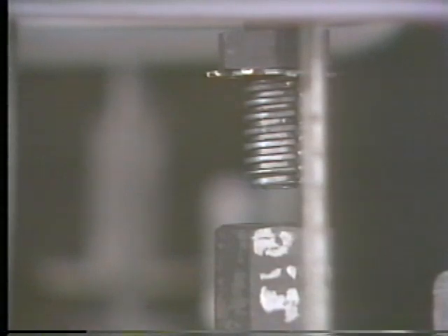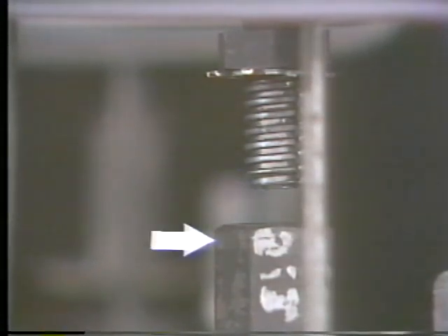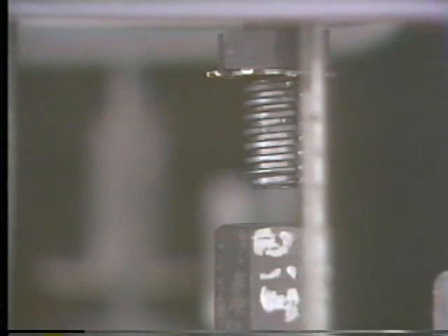With the actuator in the open position, the actuator stem has been lifted away from a hex nut that has been screwed on to the valve stem. Before the two stems can be connected, we have to be sure that the valve is seated. In other words, the valve must be closed.